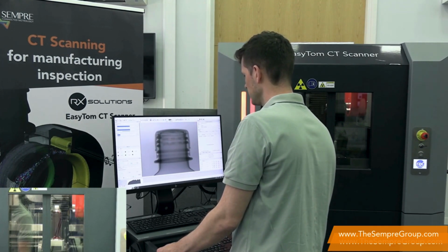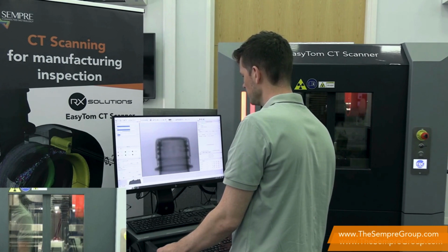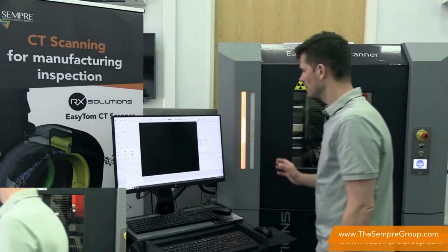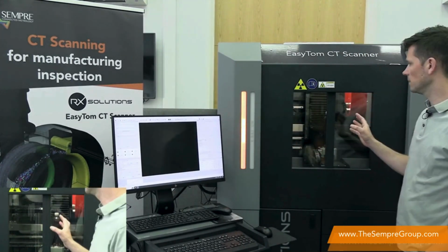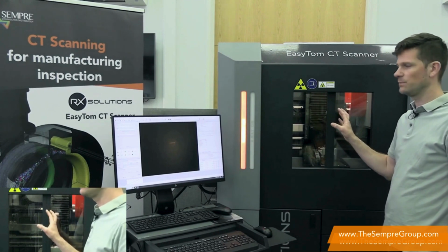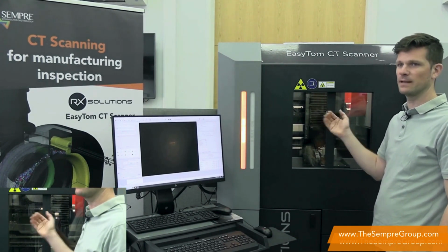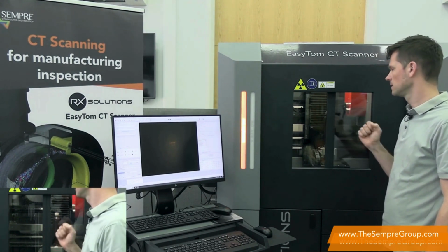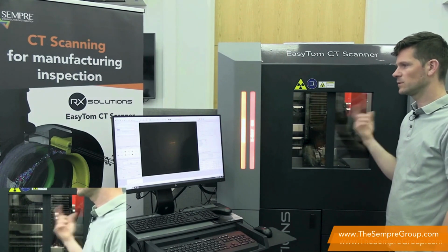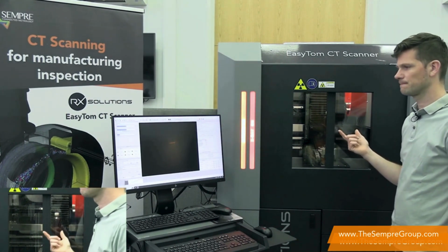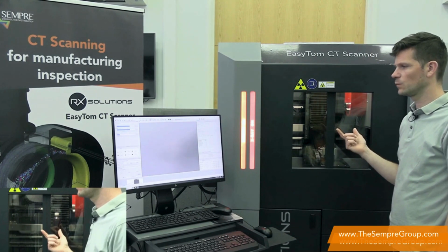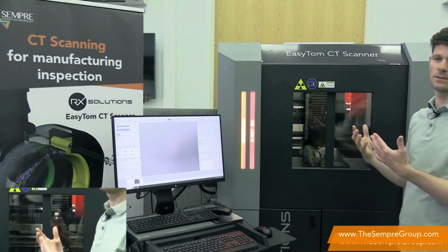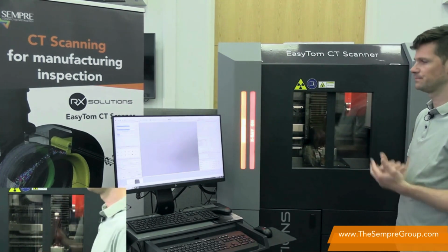First, the system asked me to remove the sample from the field of view and started tomography. So now it'll first do a calibration of the detector. It means it's going to make sure that everything which is black is black and everything which is white is white. So that's what it's doing now. Now it's creating the black image. Now it's going to put on the X-rays again. It's going to wait for 10 seconds. And then it'll create the calibration for the white.